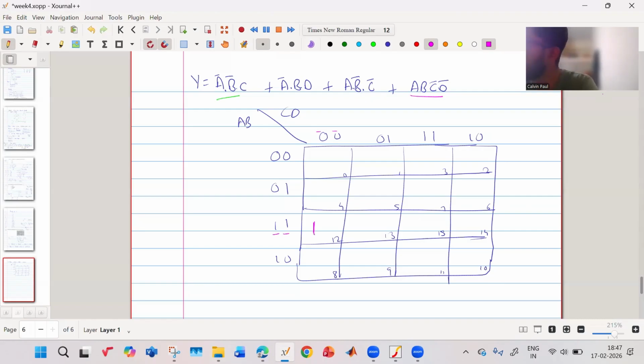If you will see, this is the sum of product. Okay, the sum of product. So we will first analyze in terms of sum of product and then we will get the product of sums. They can be interchanged. We will see how. So first thing is A, B and C bar and D bar. So A, B is 1, 1. C bar and D bar means 0, 0. So this is 1. So when all 4 variables are there, that means the size of your K-map group is 1.